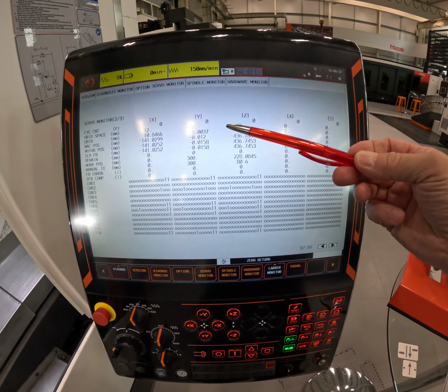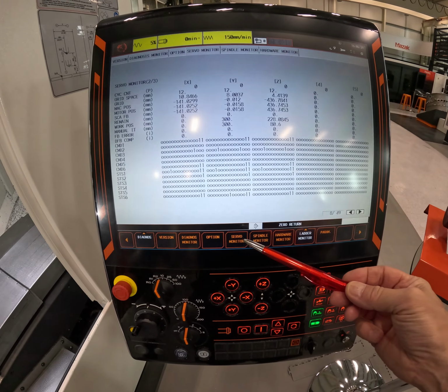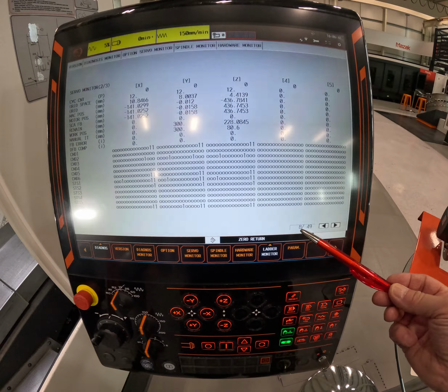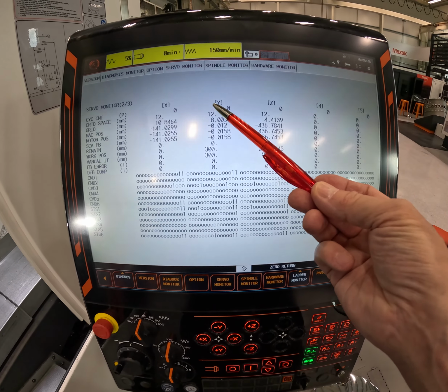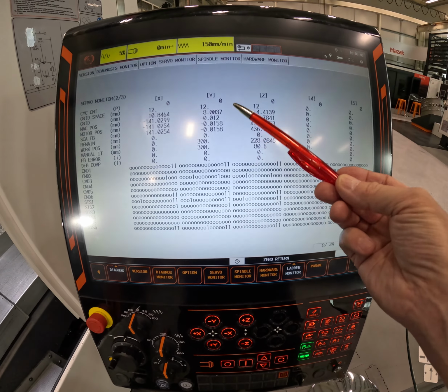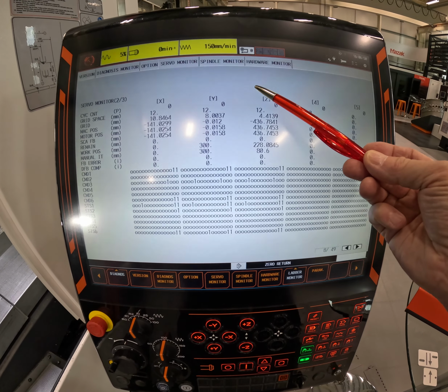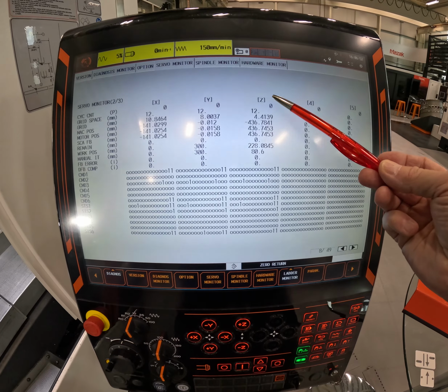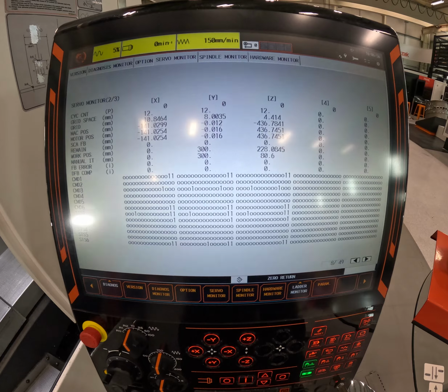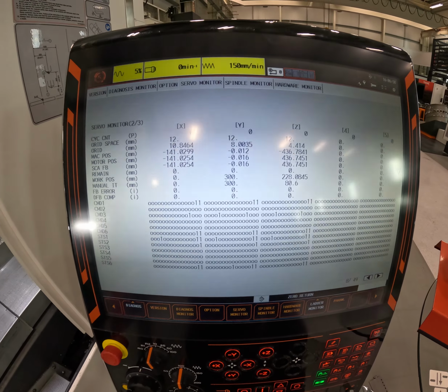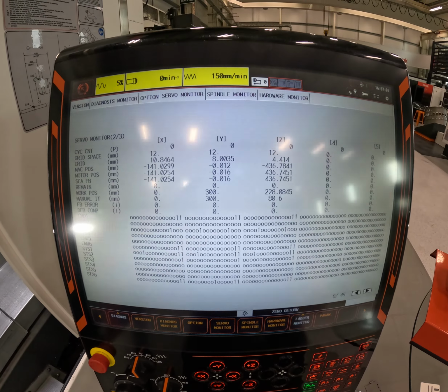We can see the feedback on our servo monitor, page 8, in our grid. We can see one full revolution, 12 millimeters, then for our 300 millimeters it's come round and stopped at 80035. This is the value we place in M16.